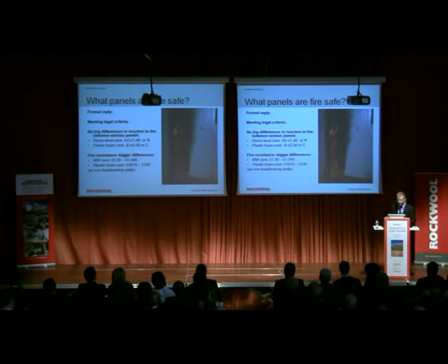If you look at reaction to fire test results measured mostly by the SBI test, you always get A2 or B, sometimes C class, regardless of the combustibility of the insulation, which is in between the steel sheets.